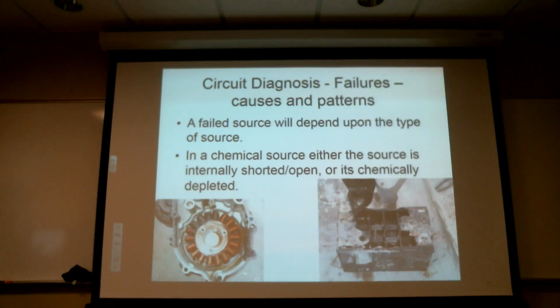Most of the time when you have a battery fail, it just internally shorts, gets a little warm, and instead of putting out 13 volts, it puts out 9 volts. Or maybe 2 start to go and it gets even worse, right? And when you put any load across it, it drops down to 3 or 4 volts, which isn't nearly enough to excite a starter or anything else.